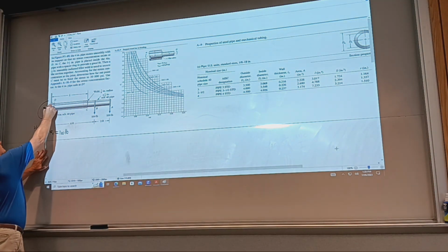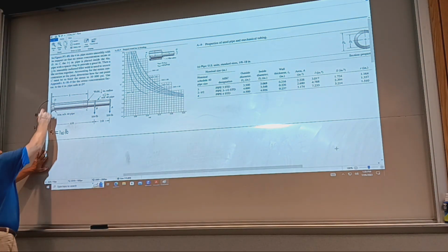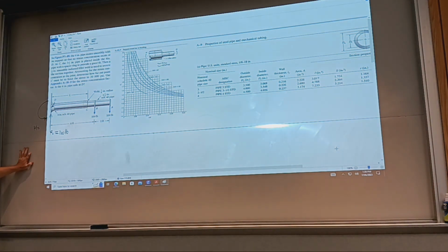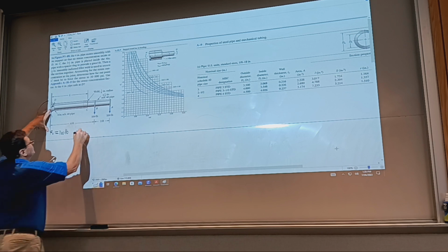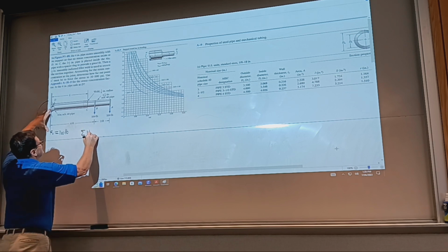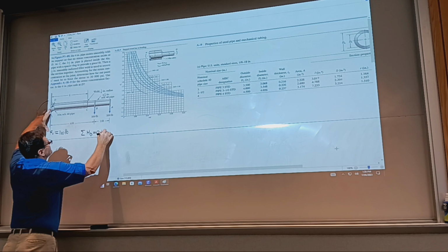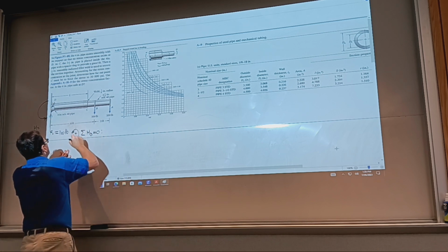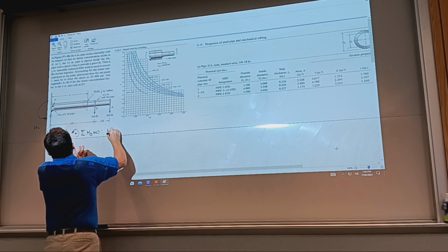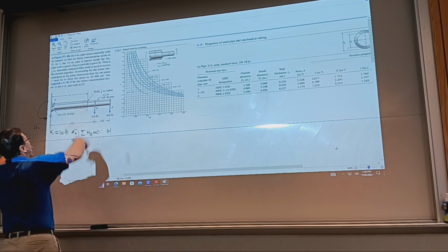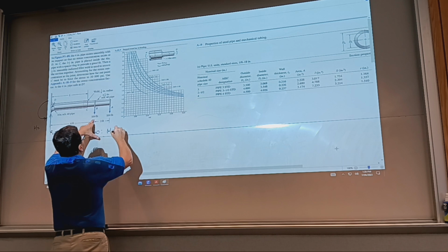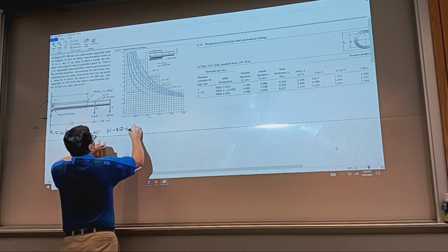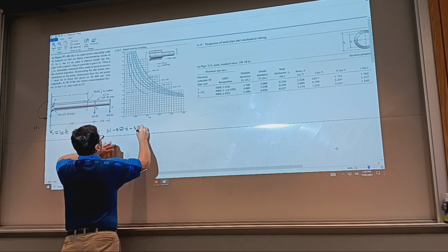So how do we get M? We have point D here. Yeah, you sum moments. So summing moments about point D to have equilibrium will give us M. And I assume positive to be counterclockwise, I have M, and then I have positive, negative 350 times 6, negative 350 times 8.